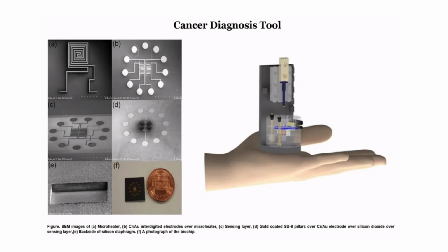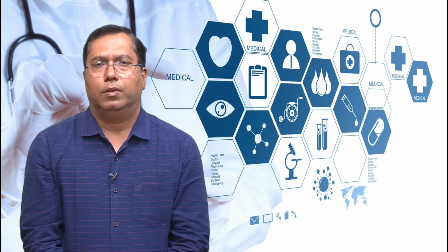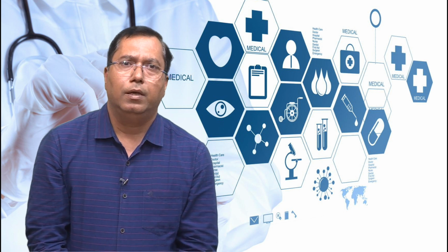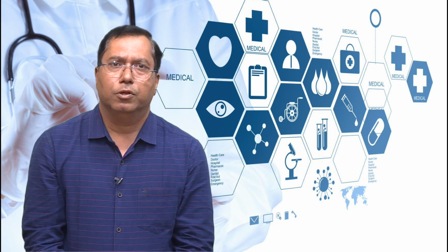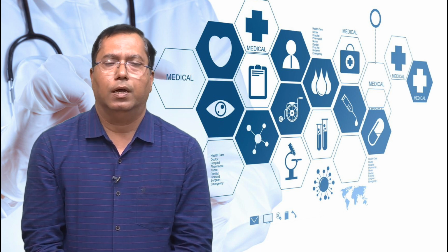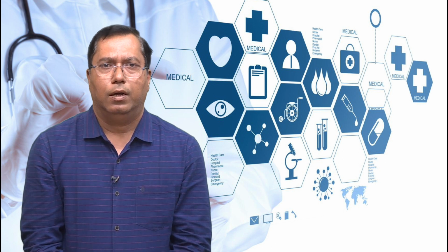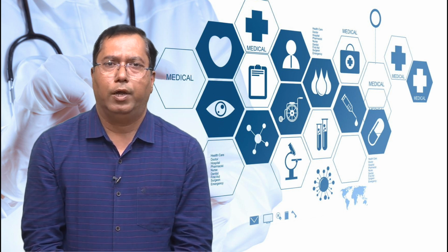There are interdigitated electrodes, which show the electrical property of the tissues, and there are two electrodes which show the thermal property of the tissues. So the basic concept of this tool or chip is that we are using the piezoresistive sensor, the interdigitated electrode, and the thermistor or two electrodes.